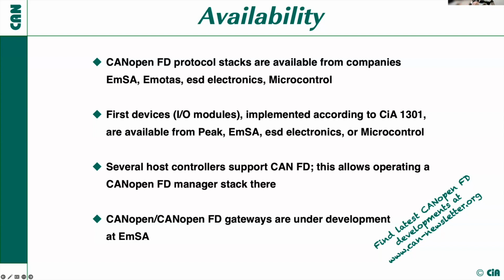With the drives, I think it's rather easy: if you want to have CANopen FD, as many of them are FPGA-based, you might get it with a corresponding stack. The host controllers often support CAN FD in the meantime, so you can also set up a CANopen FD manager stack there and make this host controller operate as a CANopen FD manager. There, I don't have a current update, but maybe at the end Olaf can say something. I know they were working on a CANopen FD gateway. Whether it's now available commercially, I don't know exactly.